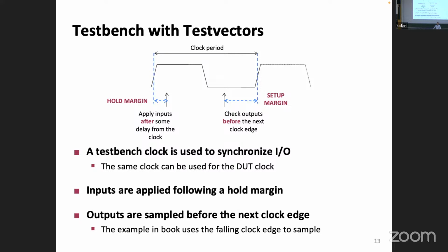For the test inputs, they have to test all the inputs for all the different states you can have in the machine? Well, that would be exhaustive testing, right? So we talked about that. That will prove to be impossible for most circuits. There will be very few circuits where we can do this, because if you have, let's say, n inputs, you have 2 to the n possibilities.